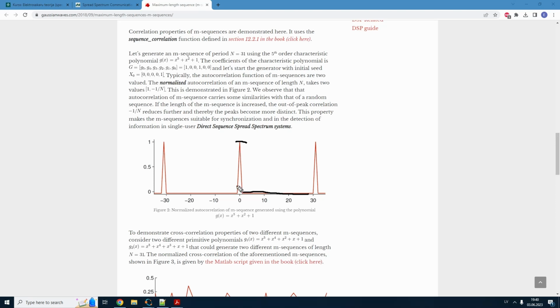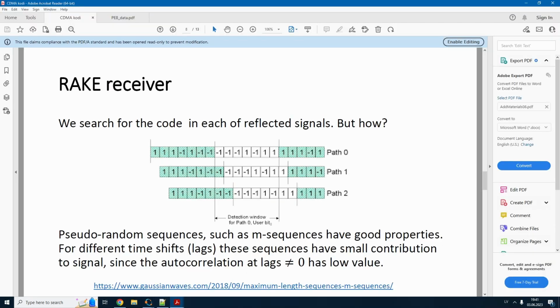There we used the cross-correlation function between different sequences, which we assumed under normal operation would have to be the same, but because of noise it may not be so. Here, however, we intentionally take the same sequence twice and calculate its correlation function. I will show you during the practical exercise how the real cross-correlation function for this sequence would look if we don't repeat it periodically, and you will see that it still produces the maximum value at zero shift. This is very good for us, as it will allow us to make a search for the sequence.